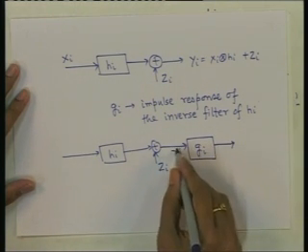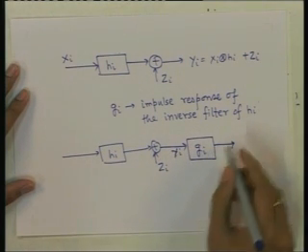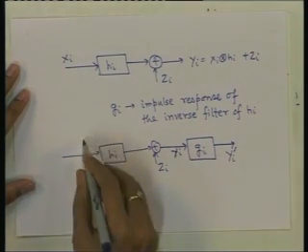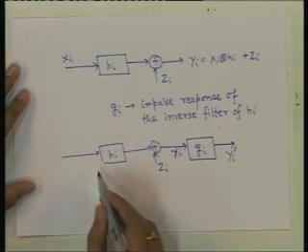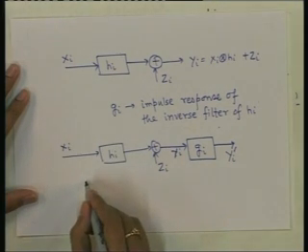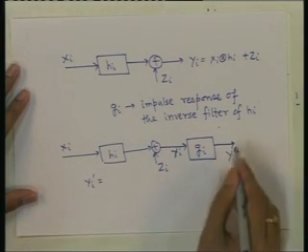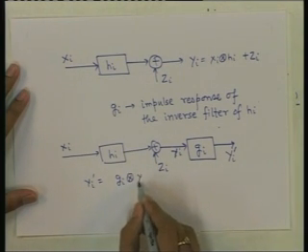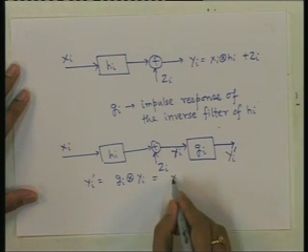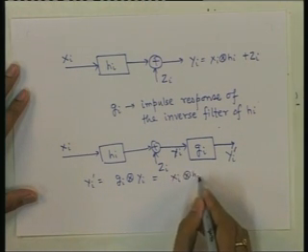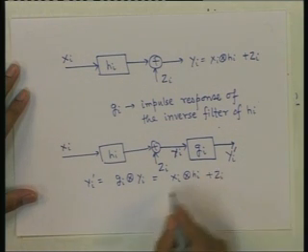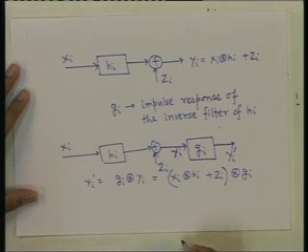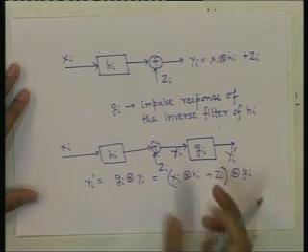This is Yi we actually received, and then we passed it through Gi. Then we have another signal, let us call it Yi prime. Then what is the relation between Yi prime and this Xi? Yi prime, this discrete time signal, is Gi convolution Yi, which is nothing but Xi convolution Hi plus Zi. So, this convolution Gi, this convolution this or this convolution this, they are the same things.